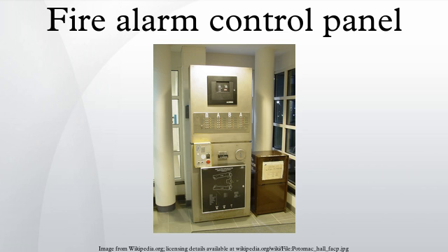Gradually, later installations began to feature components and features of modern addressable systems. These systems were often capable of controlling more than a building's fire alarm system without any type of alarm or trouble condition present. While the main panel was the brains of the system and could be used to access certain functions, fire alarm controls were usually accessed through transponders. These were smaller conventional panels programmed to communicate the status of part of the system to the main panel and also could be used to access basic fire alarm control functions. The original Simplex 4100 was meant to be used this way.